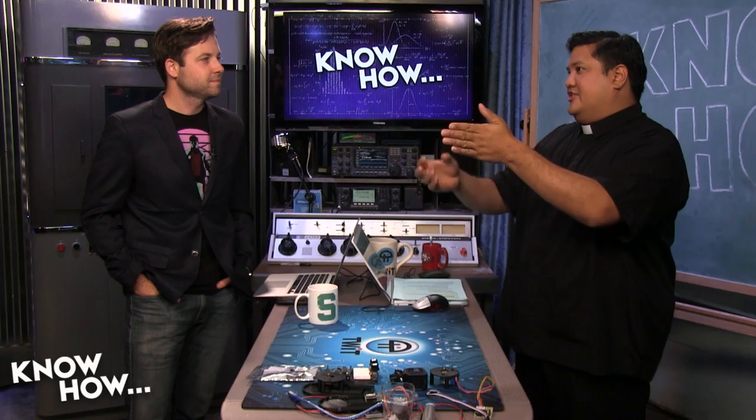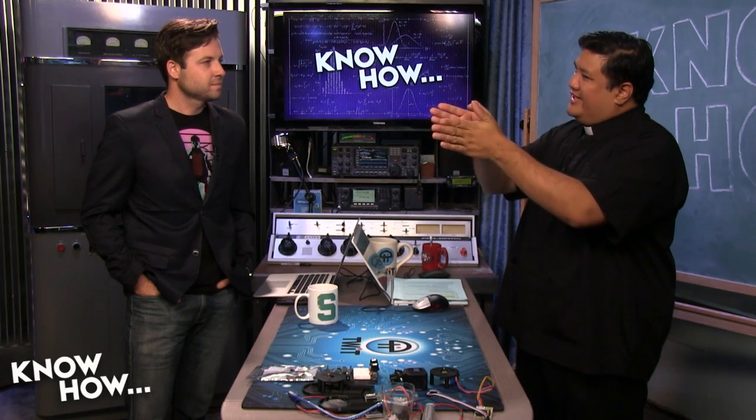A servo motor will give you more precise feedback, because it does have a potentiometer built into it, so it can kind of tell you which way it's pointed. But what we're going for is the torque advantage, and stepper motors have great torque advantage at low RPMs.